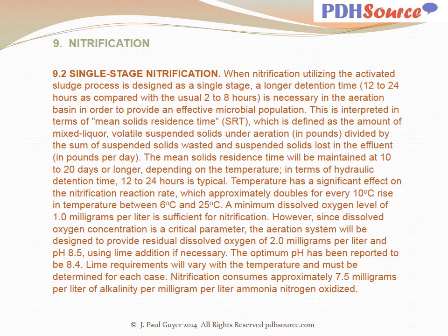This is interpreted in terms of mean solids residence time, abbreviated SRT, which is defined as the amount of mixed liquor volatile suspended solids under aeration in pounds divided by the sum of suspended solids wasted and suspended solids lost in the effluent in pounds per day. The mean solids residence time will be maintained at 10 to 20 days or longer, depending on the temperature. In terms of hydraulic detention time, 12 to 24 hours is typical.